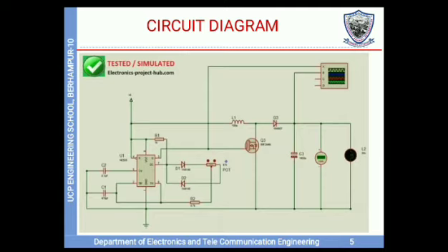Role of 4.7K at the output of the potentiometer. A 4.7K resistor is connected to the 47K potentiometer output terminal to limit the IC 555's duty cycle to 90%. This is very important because if a user rotates the knob fully, the output will get saturated, i.e. 100% duty cycle. At 100% duty cycle, the MOSFET is on continuously and creates a full surge via the inductor.